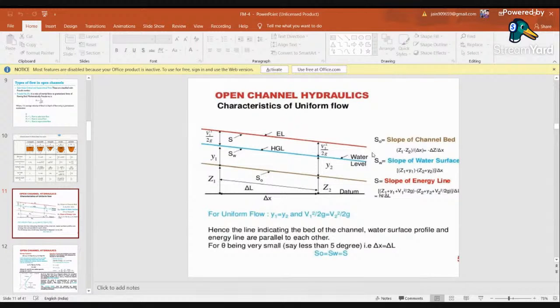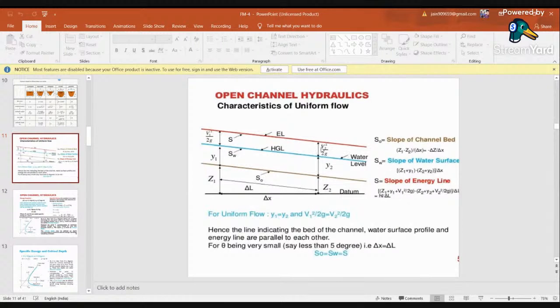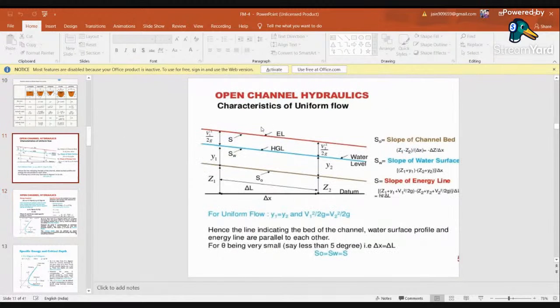Now, when we have to calculate the energies at this section for this water line, we know the equation for energy by means of Bernoulli's equation: z1 plus y1 plus v1 square by 2g must equal z2 plus y2 plus v2 square by 2g plus HL, that is the head losses. Here, the summation of all the three energies or heads is going to give you the total